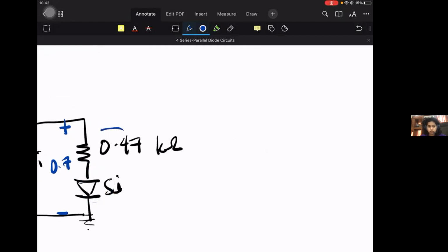Provided that there is a resistor here, no? Adding a resistor in parallel to a diode somehow changes things, okay? Because if there is a resistor and it is a power consuming device, it will consume voltage, even if only a very small amount. Maybe in this case it is a little, but it consumes voltage. So diode 2 and the resistor share the 0.7, no?